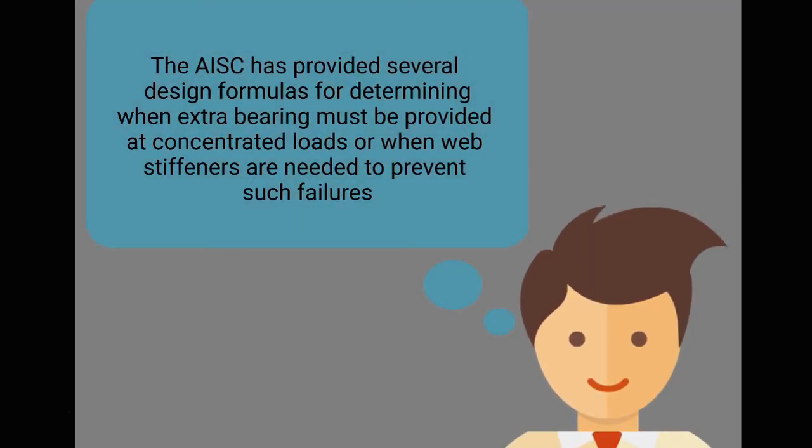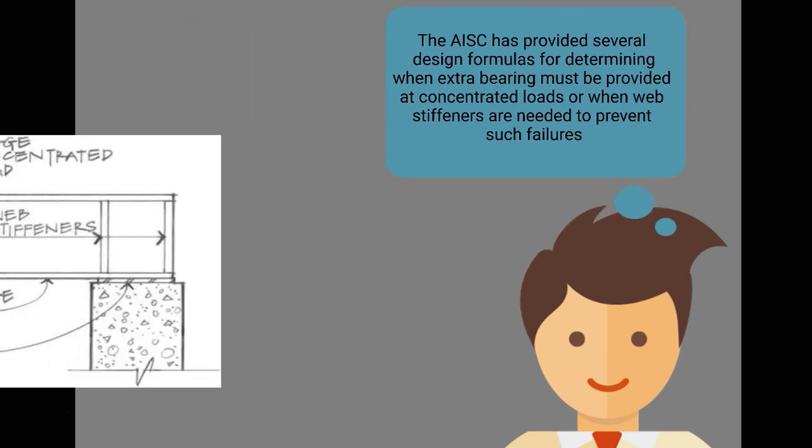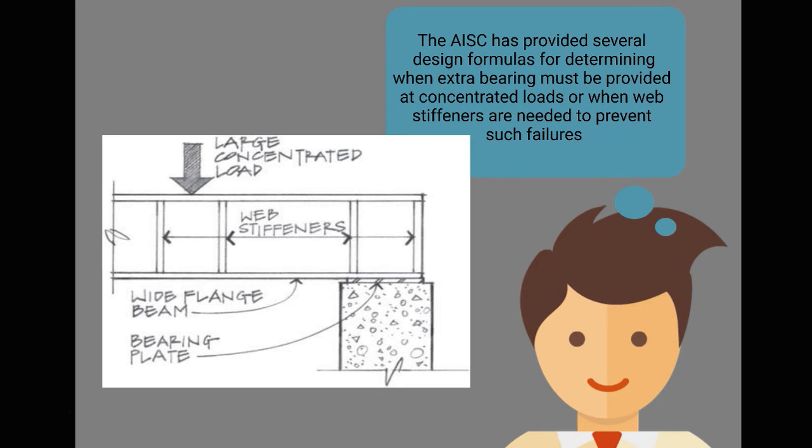The AISC has provided several design formulas for determining when extra bearing area must be provided at concentrated loads or when web stiffeners are needed to prevent such failures.